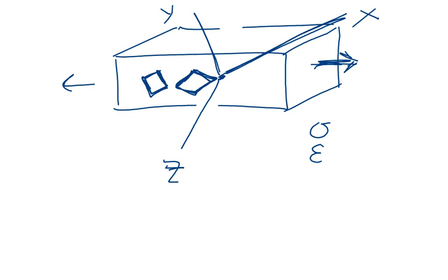Right angles are no longer right. So if right angles are no longer right, is there some shear stress that goes on here? The answer is yes. So you can see that it's a matter of perspective, and it's a matter of how you define your coordinate axes. When I have this rod that's in pure tension and compression, if I don't line up my coordinate axes with the axial direction, then I will get some shear stresses and shear strains.